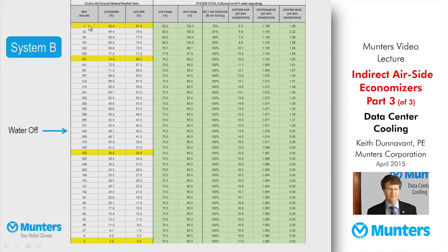So we've selected 4 different operating points, the 74.9 and 69 condition, and then here's a mild winter condition that we're going to look at in a minute. You can see that the coefficients of performance are increasing rapidly, meaning the system is performing more efficiently. We're already up to 15.8, and then at the extreme winter we're as high as 17. We're turning the water off at 50 degrees Fahrenheit, so that resulted in this bin of 49.1 and 43, where you see water utilization effectiveness go to 0.